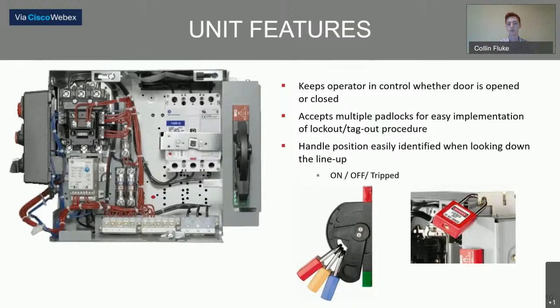So say you have a maintenance guy in the field who's doing work on a motor, and he has pulled the bucket out of the MCC. He may do a lockout tagout on that position, on that tab right there, and it prevents anybody from plugging that bucket into the MCC. Even if the disconnect handle is off, there is still not a chance that any power can come into the line side of the bucket. So just another good lockout tagout position.